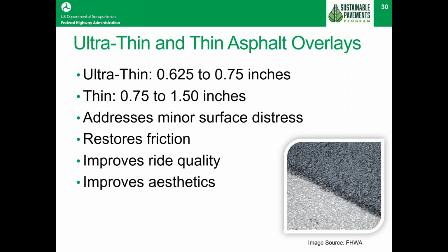Put the overlay down, and it's very effective where the pavement structure is fairly good, but the surface might be worn from traffic or some other reason. These tend to be extremely effective. They tend to give you a good surface at a lot less impact than some of the other activities that we might run into.